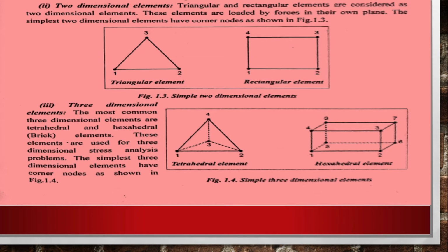And now we are going to see the three-dimensional elements. Most commonly, tetrahedral and hexahedral elements are considered as three-dimensional elements. These elements are used for three-dimensional stress analysis problems, where we use elements like the tetrahedral element and hexahedral element.